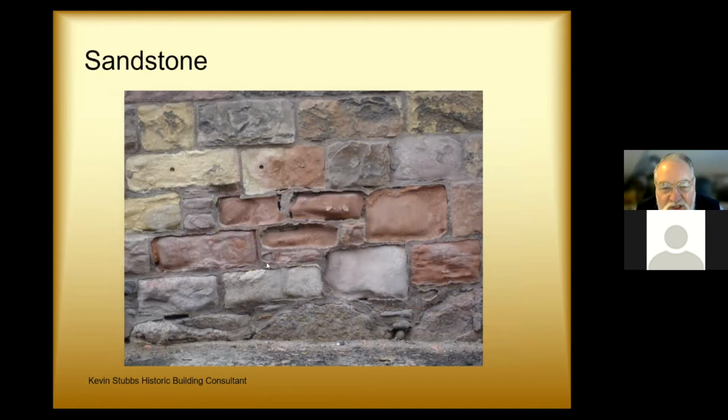Other sandstones, you get a whole variety of colours depending on the amount of iron in the soil in the area and other materials leaching in. You also can get hybrids, which are neither a pure sandstone or a pure limestone. These are calcareous sandstones and again have different weathering properties. But the big problem with most of these stones, immediately you start repointing with cement mortars, you get rapid deterioration of the face of the stonework.